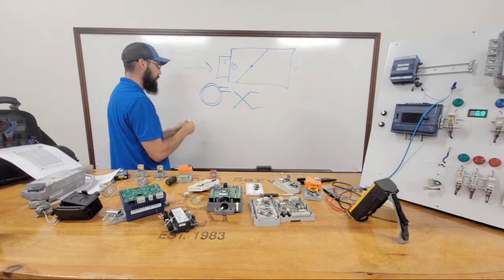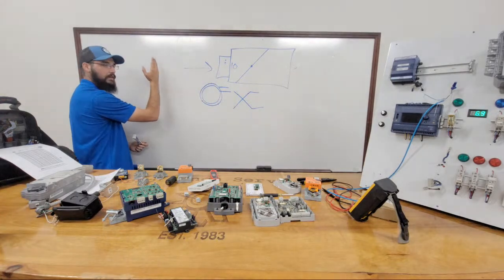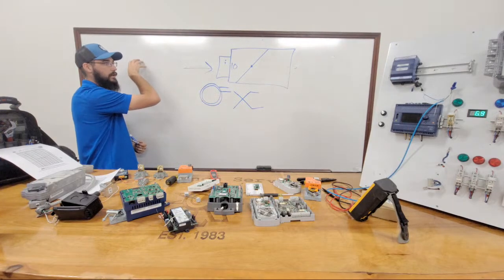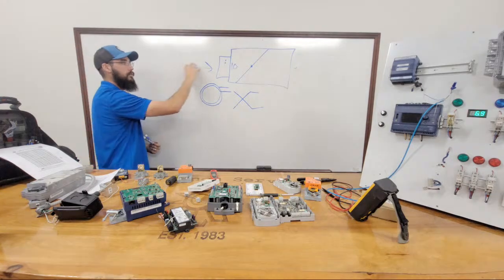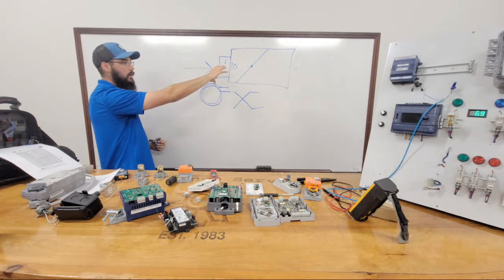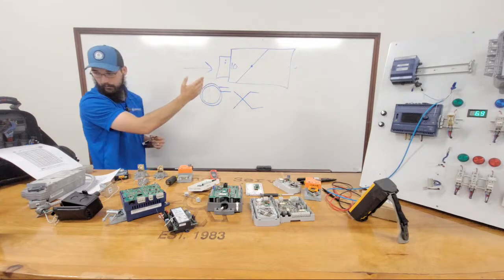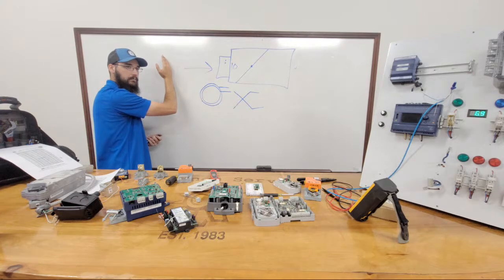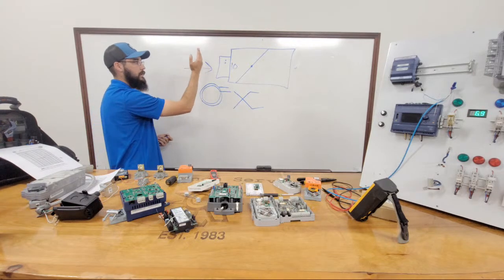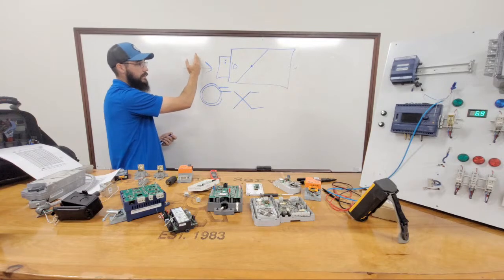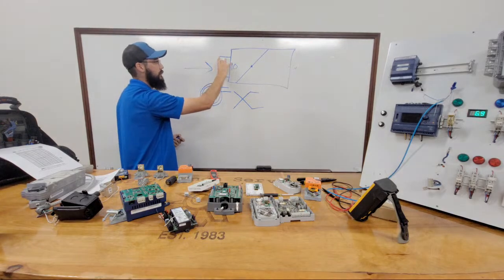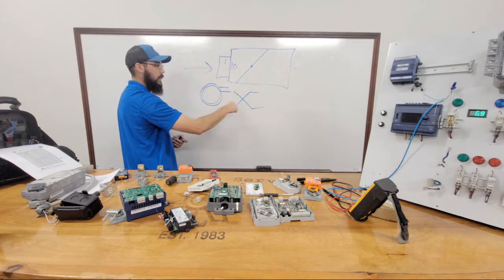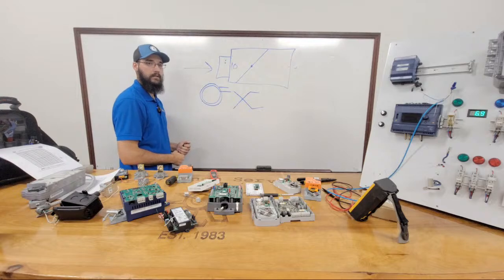And that multiplier tells you how many feet of solid ductwork is required as it comes into the box. So, for example, if you needed 6 feet of minimum hard pipe, but you only did 2 feet, or maybe they didn't do hard pipe at all, and they ran straight flex directly to the back of that collar, these pickups will never function properly, period.